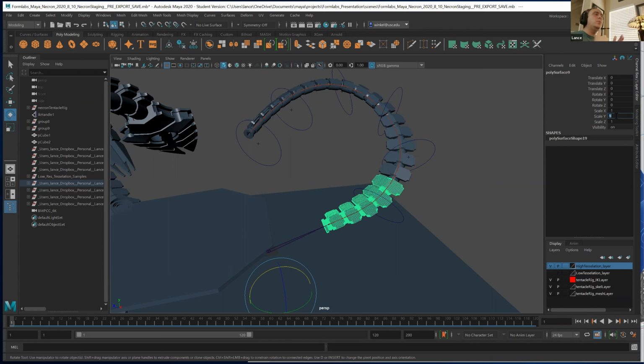So the problem with scale is if you have lots of hierarchies and you have one object that is a parent of another object, that parent object, if it has any non-1-1-1 scale, is actually multiplying the size of the universe for the other object that is its child. That gets to be really, really complicated, and it can make some really bad situations occur.